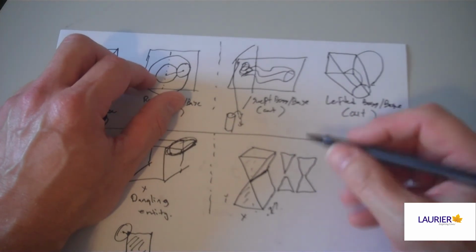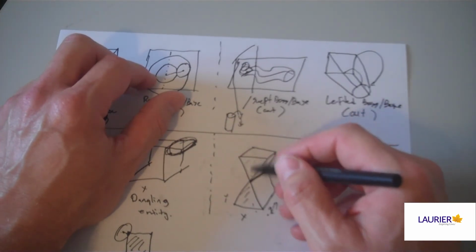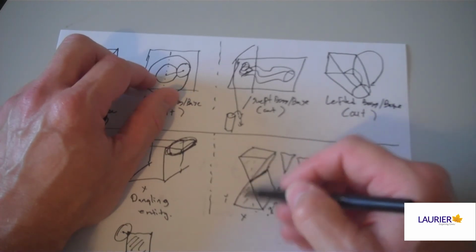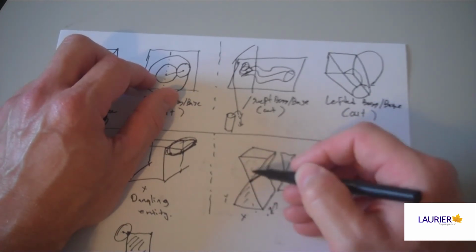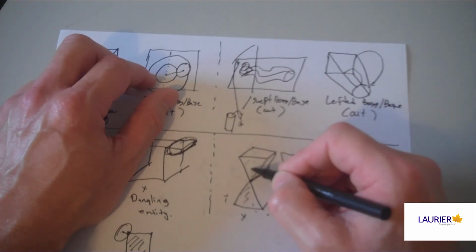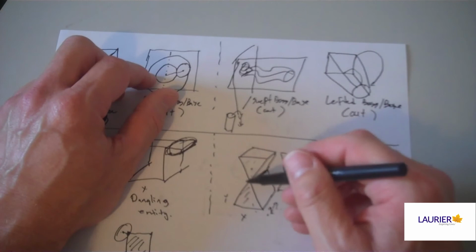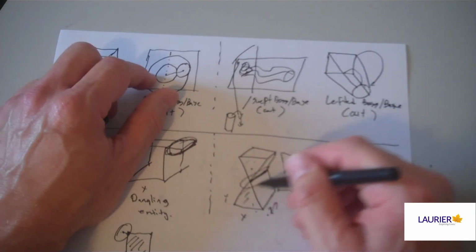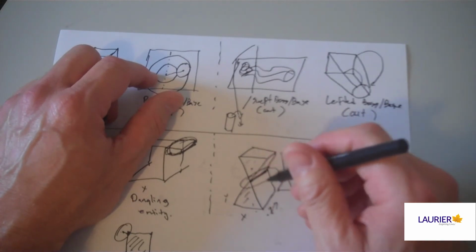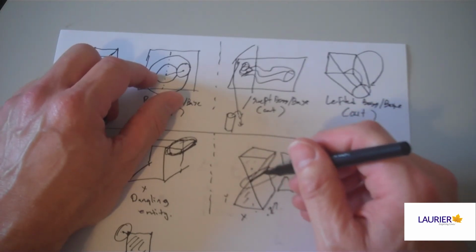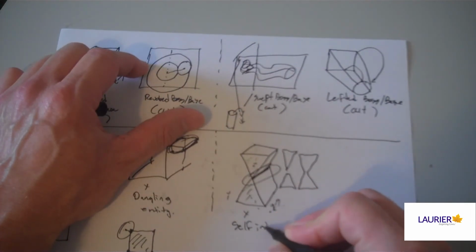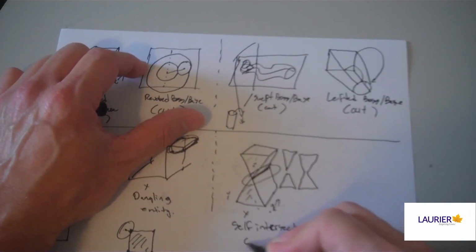To fix this, if we really do want this shape, what we can do is, instead of asking the CAD to extrude the entire thing at once, we can select this contour, and then select this contour separately. Then the CAD will kick into a mode where the mathematics can actually handle this situation. If it wasn't intended that the lines of the sketch would crisscross themselves, the other solution is to simply redo the sketch and avoid crisscrossing lines. This error is called a self-intersecting contour.